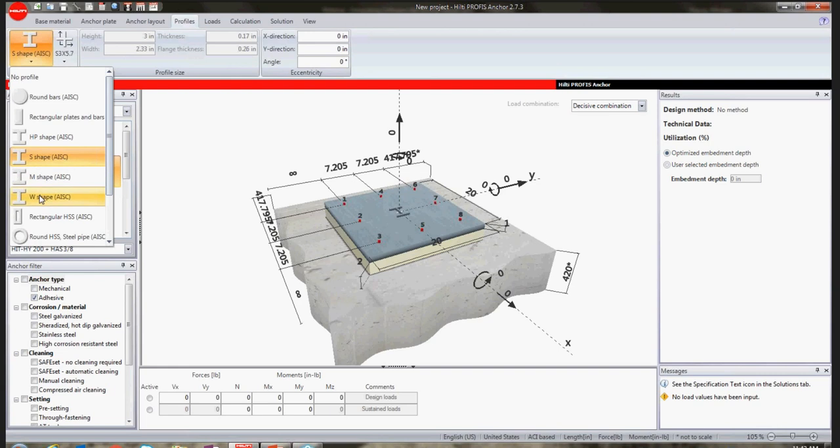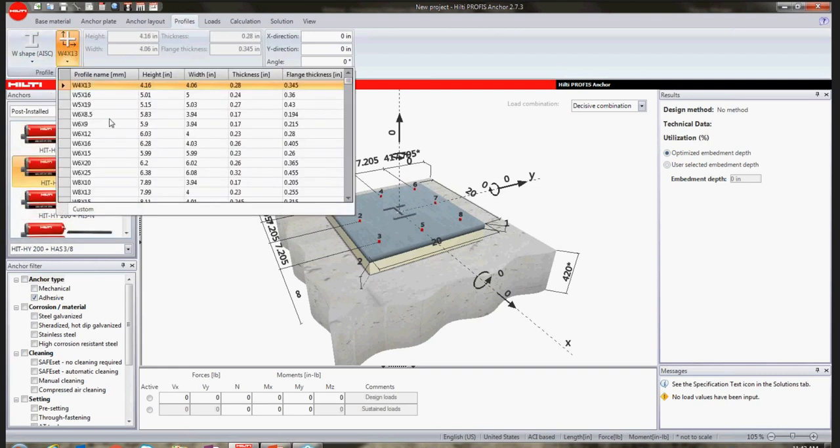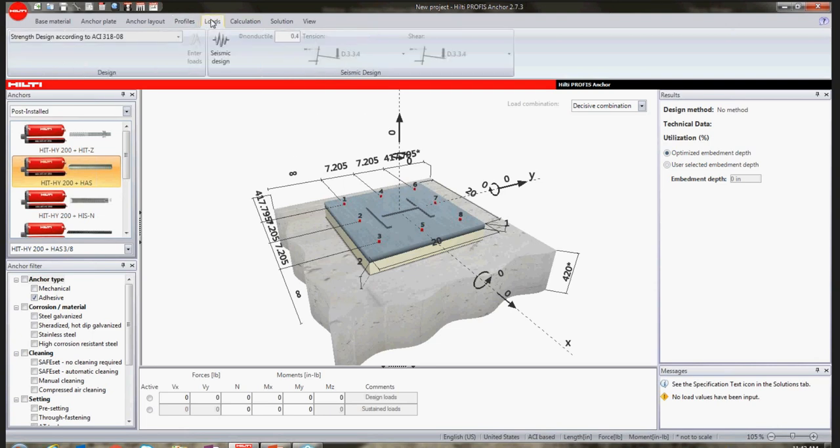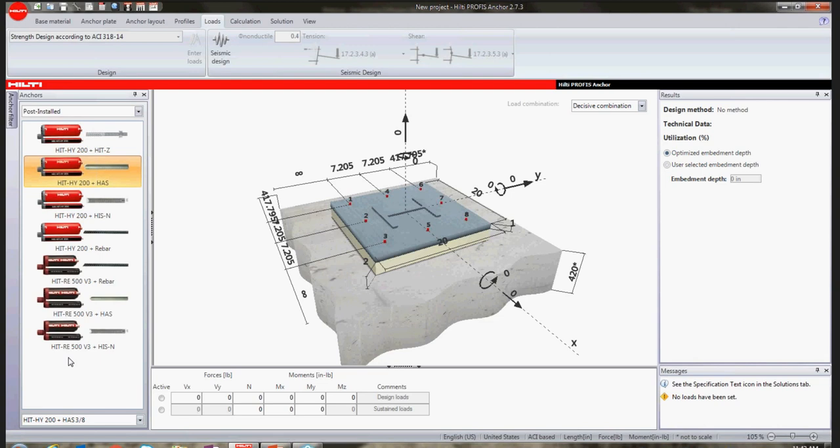And the last thing that I really want to focus on is going to be the tension and shear load utilization. So what is happening? What is the software doing? The code allows us two ways to calculate tension and shear from a combination standpoint. This is the trilinear method, where we're taking the factored load against our design capacity in tension, and then adding the factored load in shear against the design capacity in shear that's controlling. So both controlling failure modes in tension and shear. Add those together and make sure it's less than or equal to 1.2.